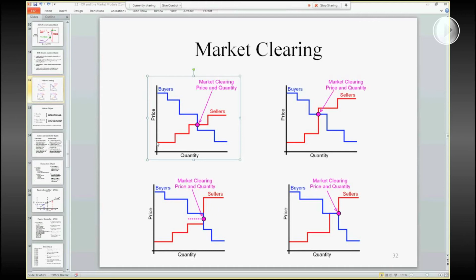And on the seller's curve, we're looking at things like, for example, a diesel generator or maybe a wind turbine or something like that that's saying, well, here's how much power I have to provide. Here's how much I'm willing to sell it for. Inside the auction, these are all accumulated together, and some kind of balanced market clearing price and quantity are formed. Now, constraints can be put on here. So, for example, you could put a constraint right at this level that says, well, that's my feeder capacity, so we can't exceed this quantity, in which case the price would be elevated to prevent that type of occurrence.